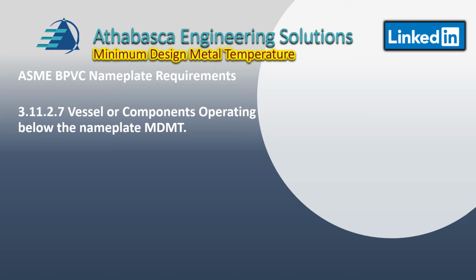Then you can reduce that MDMT, provided that you're not any colder than minus 104 degrees centigrade, or minus 155 Fahrenheit. You'll see that when we go through this in a little bit more detail. So the minimum operating temperature is minus 104 no matter what you do.